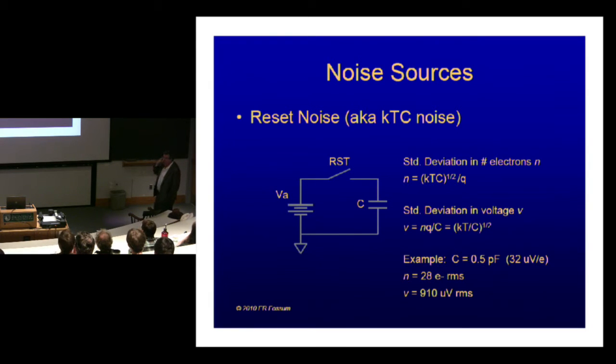This always amuses me: you'll find a lot of circuit guys who will go to great lengths to try to derive this from the frequency response or noise response of a MOSFET transistor or something like that. And of course you better get the same answer when you do that. But the noise is actually very fundamental. Even a perfect switch is still going to give you some kTC noise.